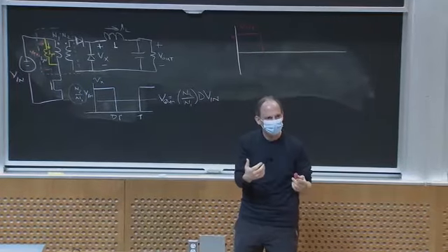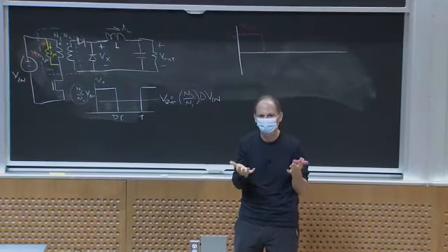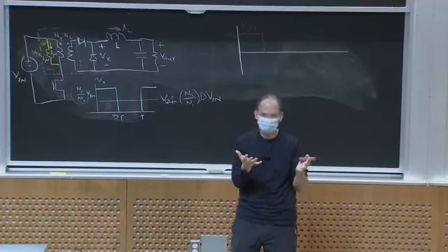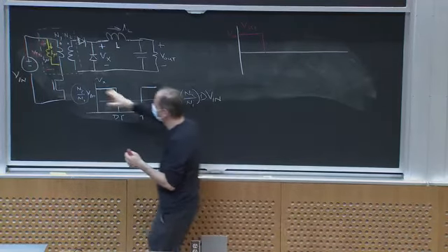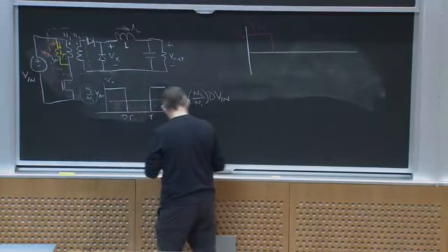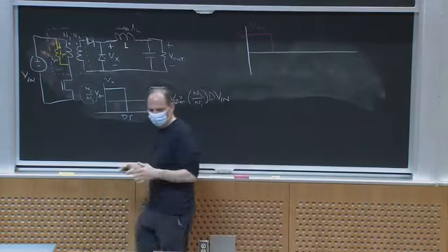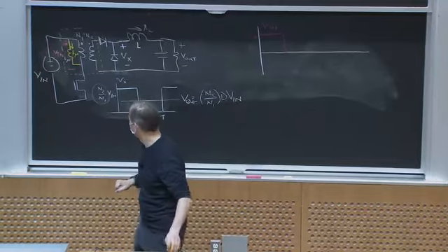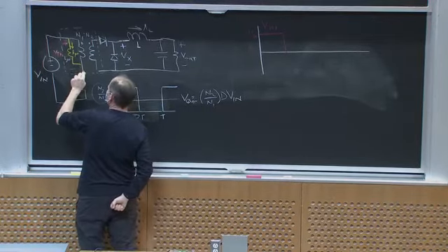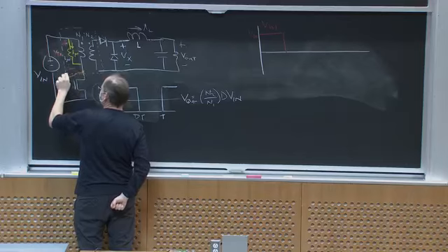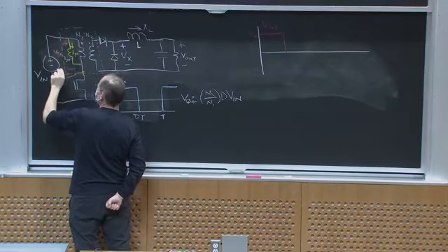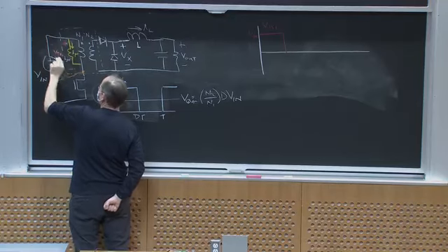Okay? So what can I do? I've got to provide some other place for that magnetizing current to flow. And in the process, I need to apply a reverse voltage on V mu 1. Okay? Now, there's a lot of ways I could do that. One very popular way is to provide a voltage here and maybe put, say, the equivalent of a Zener diode here. And then I will put a reverse diode here.